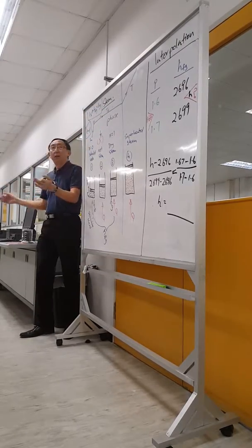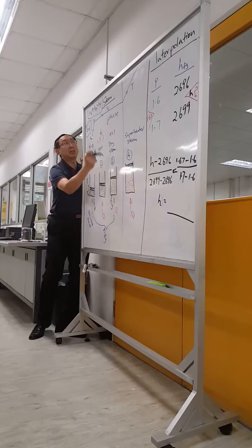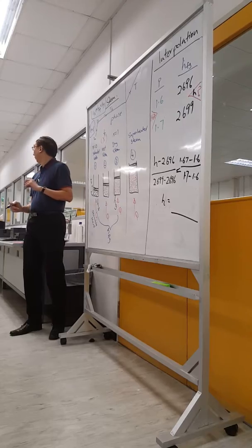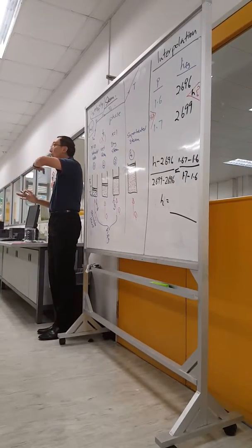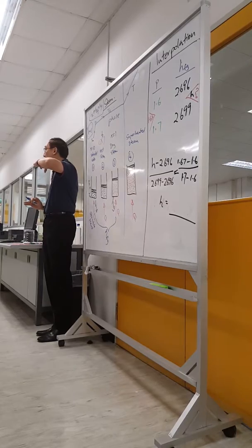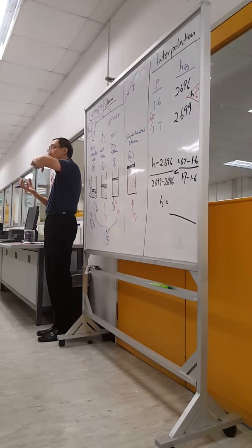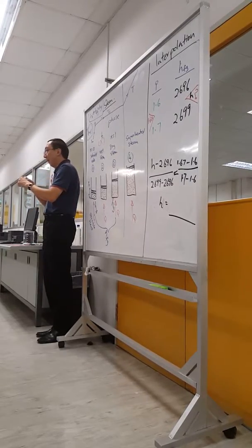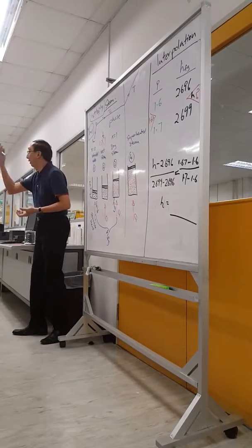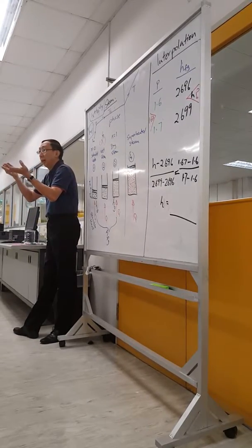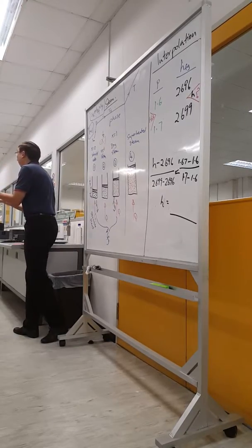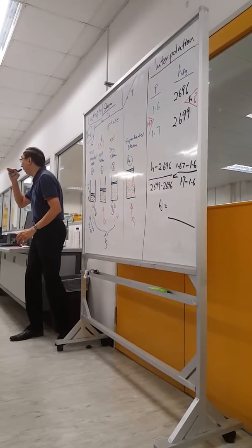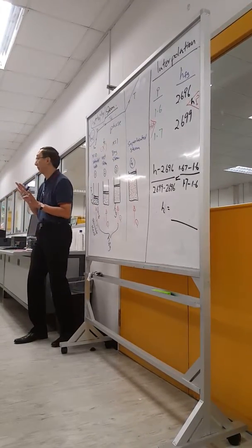Let's say if water here, if this is 100, during this change to dry steam, if I add in heat, it still remains at 100 degrees. Temperature never changes because it reaches its saturation, the maximum for water. It's only the next thing that you add in energy, I change from liquid to gas. Just like in your fridge, you have water, you put inside your freezer, what happens? The liquid changes to solid, right? So that particular phase change there, the temperature will remain the same. It's just the energy level that is different.